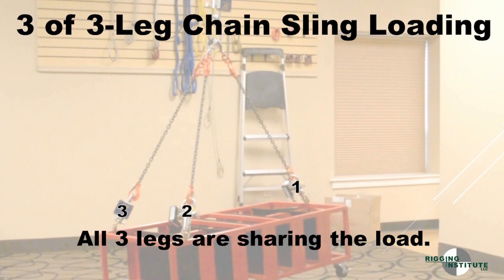The following test shows a 3-leg alloy chain sling hookup with all 3 legs supporting the load. Sling 1 is supporting half the load, and slings 2 and 3 are sharing the other half of the load.